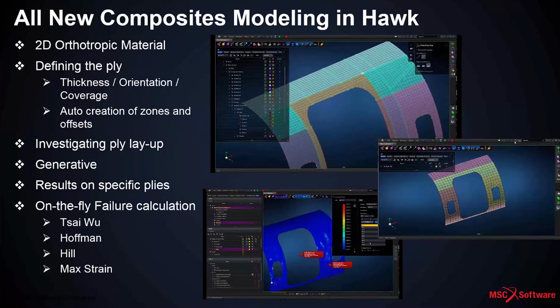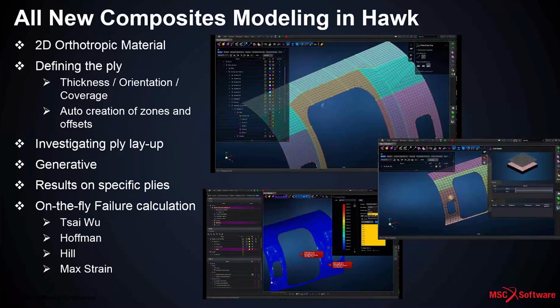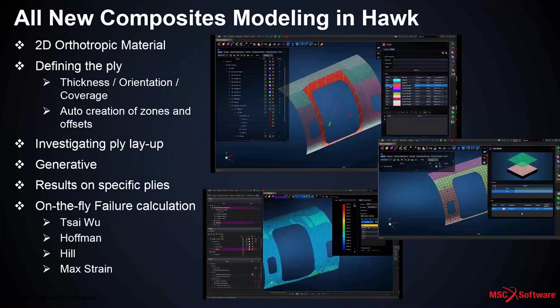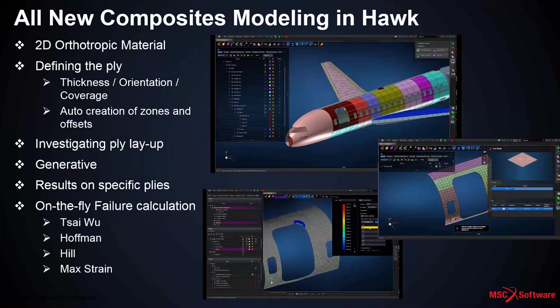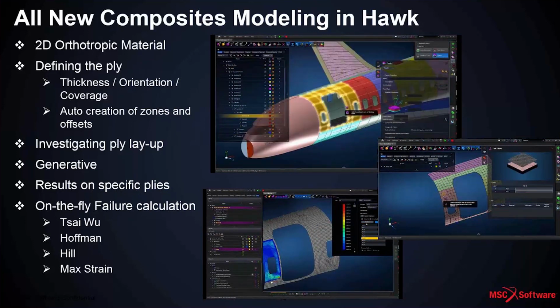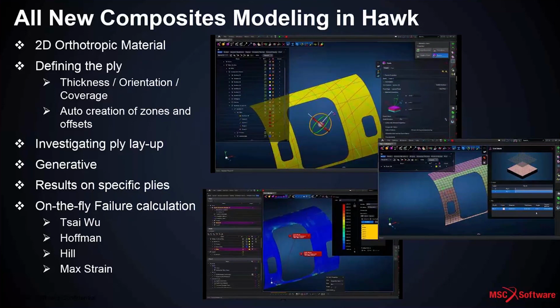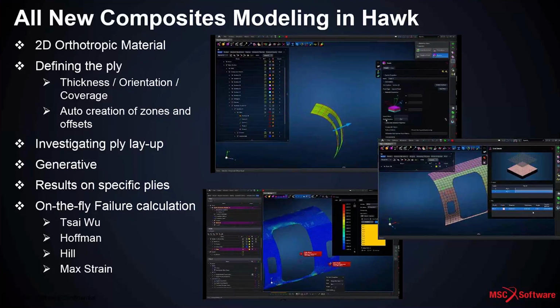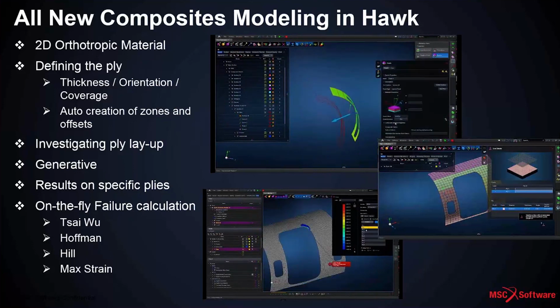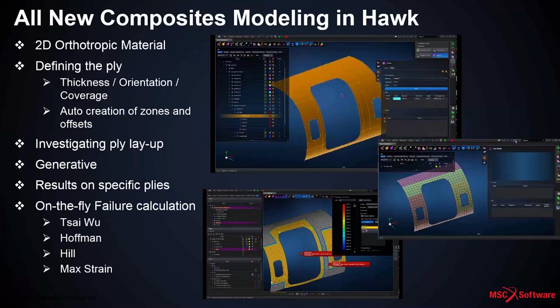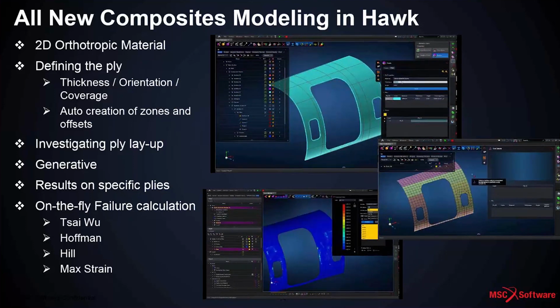And you know, change is not just about the layup itself, but it could be model changes. Like you may find you need to remesh in an area to capture the results better, or there may be some geometry tweaks that are going to happen. Both of these changes are once again automatic in Apex because of Apex's generative capabilities. In a nutshell, what you're really going to see today is that in Apex, your layup information is mesh independent.